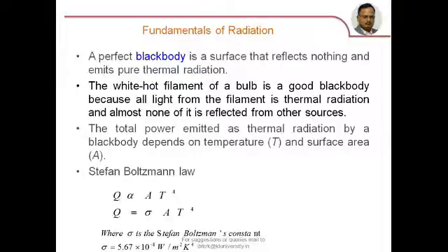So the fundamental thing which we should know in radiation is that whenever a body or a surface temperature is greater than 0 Kelvin, please note it is not 0 degrees centigrade, 0 Kelvin, that body, by virtue of its temperature, emits energy in all possible directions in the form of electromagnetic waves, and that mode of transfer is called radiation.